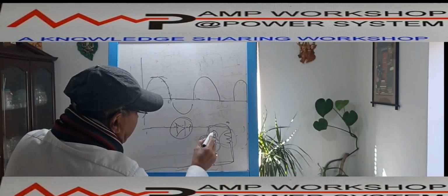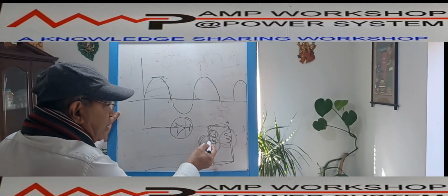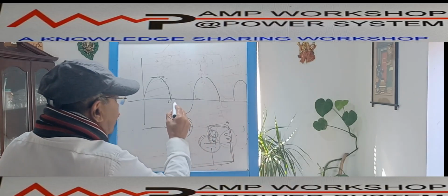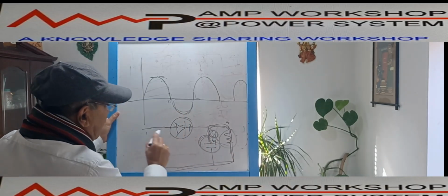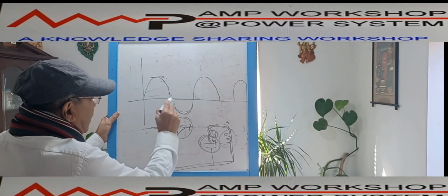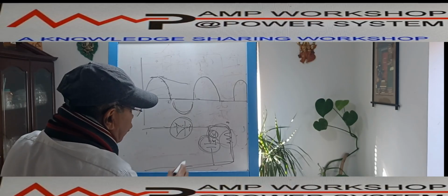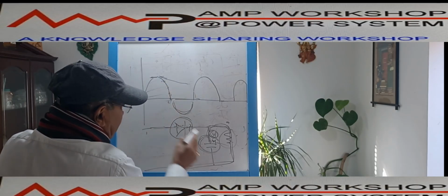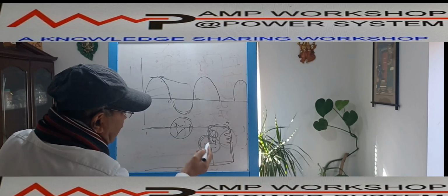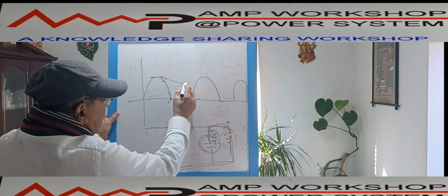It becomes negative, but the capacitor is at 4 volts and is only slightly reduced, so the capacitor voltage will reduce. That means in the negative half cycle, when the input voltage is not there, due to this capacitor there will be voltage over here. Because the capacitor is discharging, the capacitor voltage will be gradually reducing.